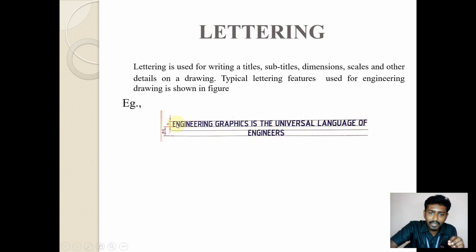So here I have taken one line, and coming to the next line, okay, it is the same sentence continuing to the next line, for which I have added a space between the two lines of 1.5 mm. It is a rule, okay. If you are writing the note, it should be 5 mm in height, for which you have to make the guidelines.